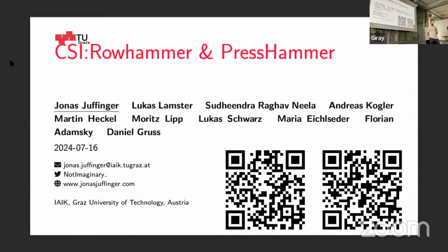But then if you try reducing it a little bit further down, let's say you go from 1 volt to 0.975 volts, it's just a little bit of reduction, right? And then you see bit flips all over.